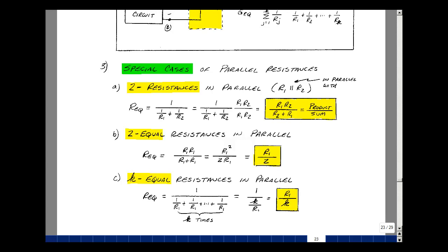Now you could do this by taking two 2K resistors, which are each a half a watt apiece, and putting them in parallel. 2K in parallel with 2K would be 1K, and now each resistor has the capability of a half a watt, and so in total 1 watt.